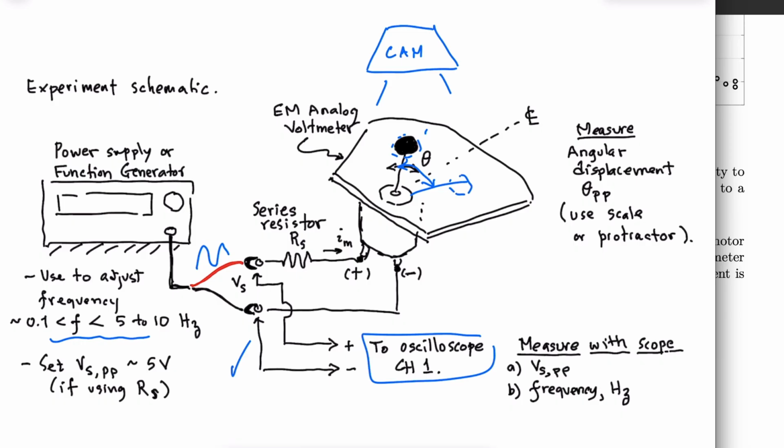When you think about your experiment design, you have to know what range of frequency to use, what amplitude, and so on. And also note, one thing that we're not measuring here is phase. It's just too hard, because we're measuring using vision and analysis with OpenCV, we're not coordinating the measurement of theta at the same time as the input voltage.